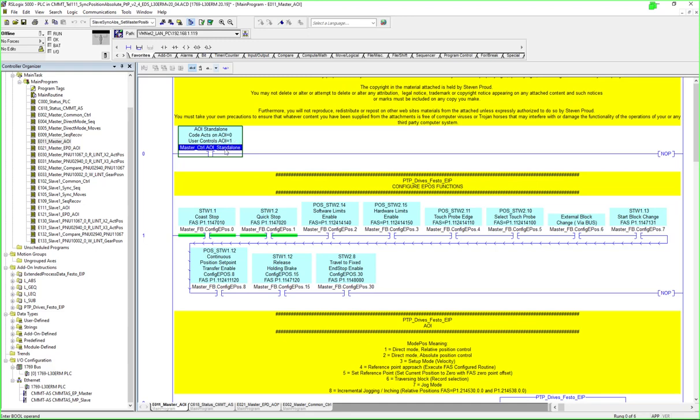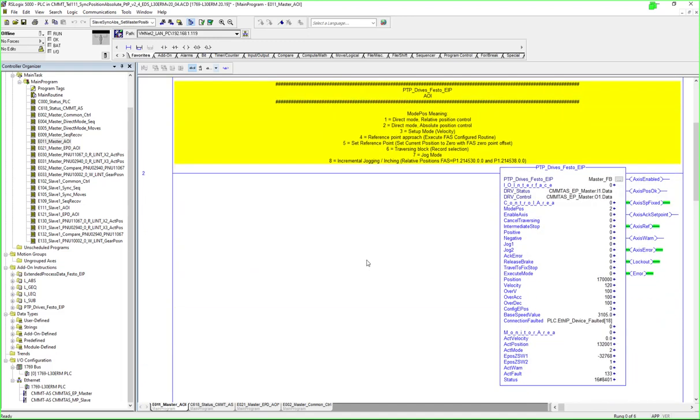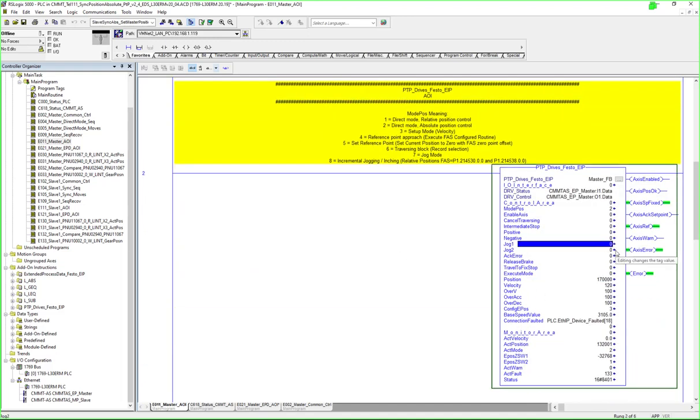When this is off, the code is working, and when this is turned on, then the user controls this AOI. So I can literally come in here, put a 1 here, and it should start to respond, if I'm online, of course, and use this. So that if I ever want to try something out, I can go back and forth. So that's what that bit's for.